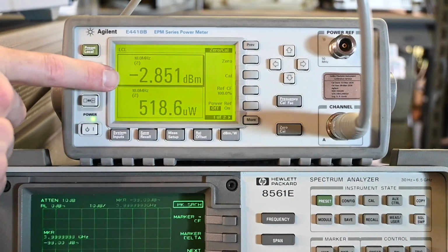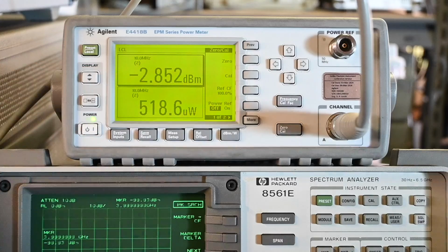And you can see the level is actually minus 2.8 dBm. So again, the spectrum analyzer was not accurate in its reading, but it's getting closer and closer the higher the frequency goes. I've played around with it a little bit, and there's no major change when it jumps from band 0 to band 1. There's no major improvement. It's just a gradual improvement basically across the entire range of the spectrum analyzer.